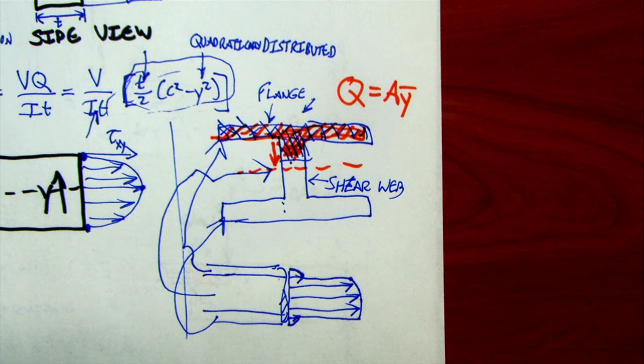So if you think of it from more of a Mohr's circle kind of view, we can predict what direction those stresses are going to be in. So if we just add a lot of strength in those directions, we're set. And the neat thing with composite materials is that you can do that very directly. So that's fun.